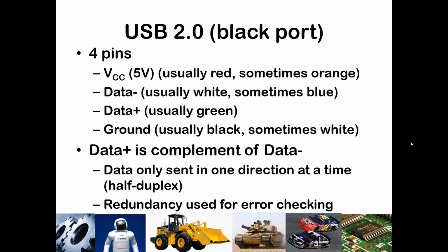And so the data plus and the data minus actually carry the same data, but one is just the complement of the other. And that allows us to still send data in one direction at a time, but the redundancy is for error checking. So if at any point your data minus signal and your data plus signal are showing the same polarity, either they're both logic 1 or logic 0, that indicates that there's an error in your transmission. But if you're seeing that one is the exact opposite of the other, that is the normal operating procedure for